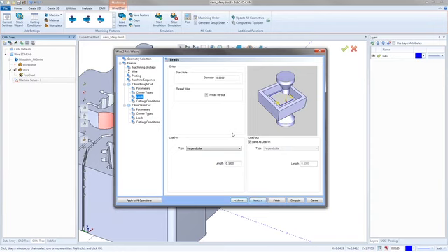Right here are the leads. So your start hole diameters are more important when you're doing a coreless kind of cut. A coreless cut is kind of like a pocket. Instead of just making one pass, we're going to start from the inside and work our way to the outside, taking small passes to get all the way out there. Well, with the start hole having a diameter, you're able to come in and tell BobCAD where the hole is, so we can center up with the hole, and also what size it is, so we know what area we don't have to worry about. If you put a 1/2-inch hole down the center of your part, we don't have to cut the 1/2-inch area that was drilled out.